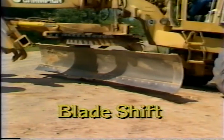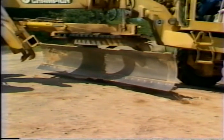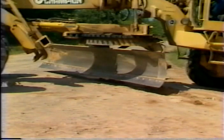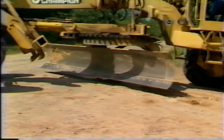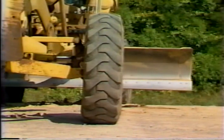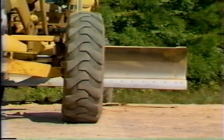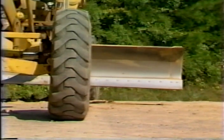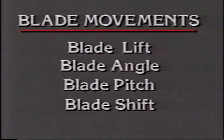The last movement is blade shift. Blade shift is the extension of the blade sideways beyond its normal position. The extensions vary depending on the job to be done. Blade shift allows the motor grader to reach areas farther away from where the tires must run. This is useful to avoid running the motor grader in wet areas. So, these are the 4 basic blade movements: blade lift, blade angle, blade pitch, and blade shift.